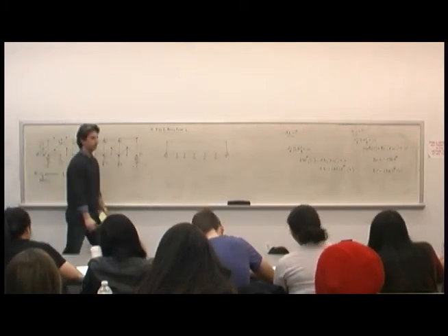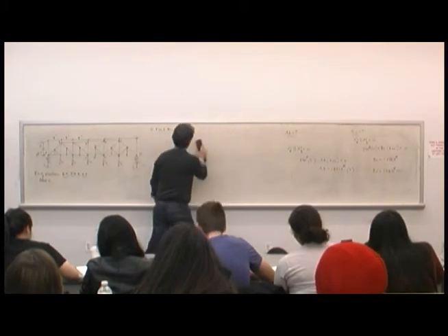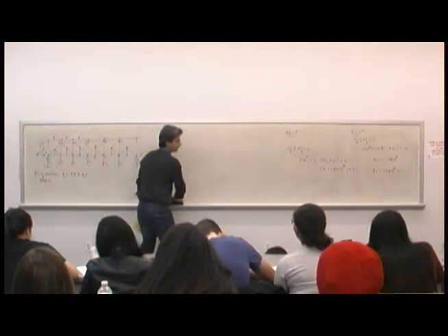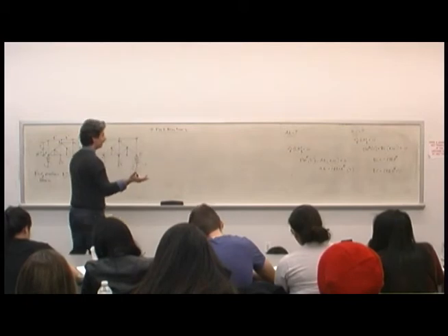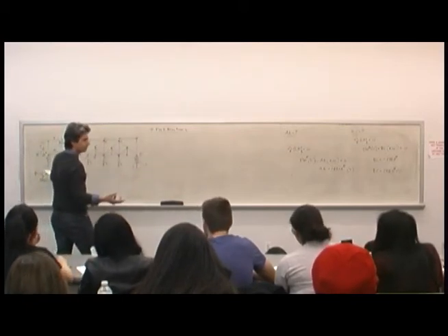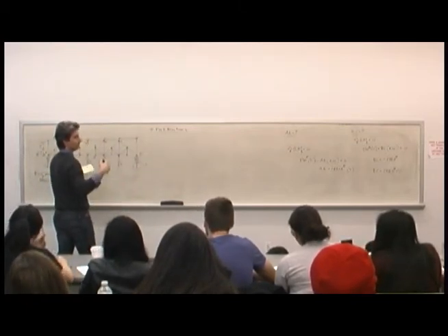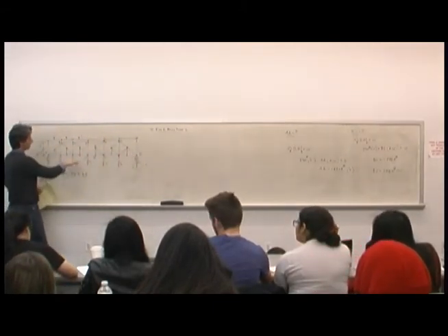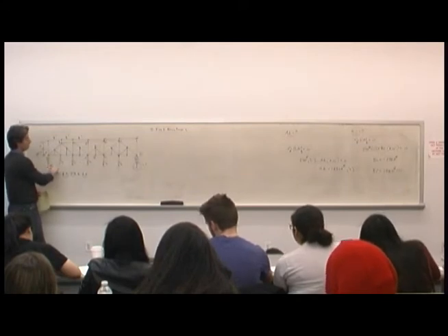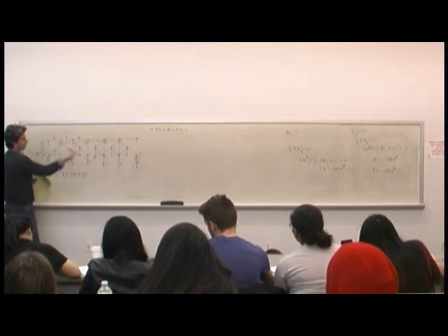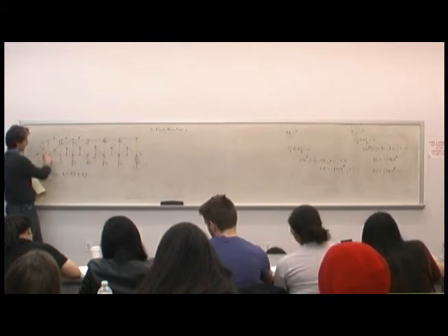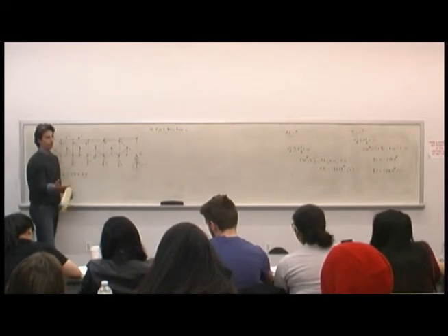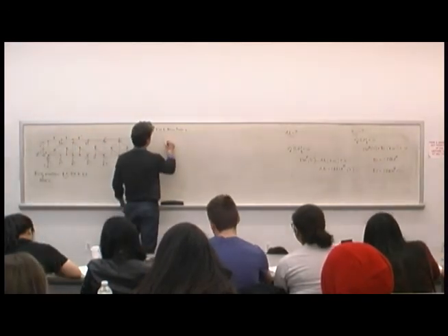So how do I solve it? Well, I can't sum forces. You can sum forces in the y direction, but what's it going to give me? It's going to give me 2 unknowns. Then I'm going to need a moment equation. So moments at A. Just do moments at one side or the other. I sum moments at A, which gives me 1 unknown, right? Just like a beam problem. So sum the moments at A.